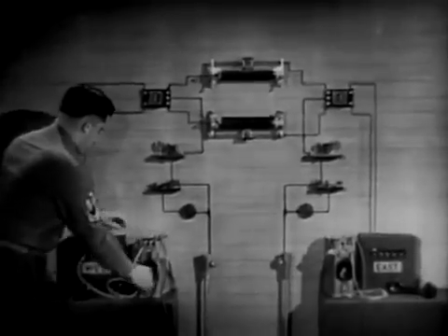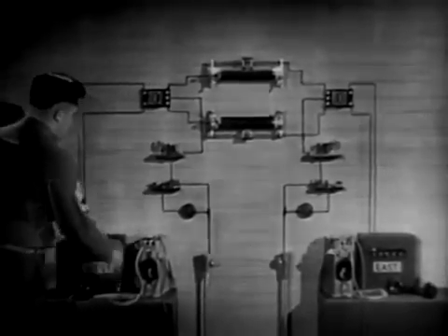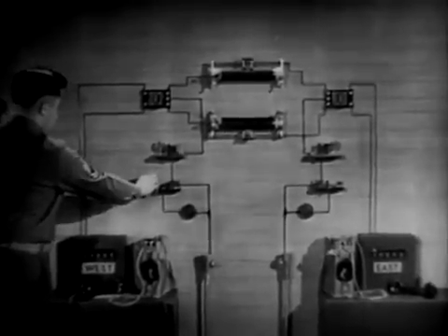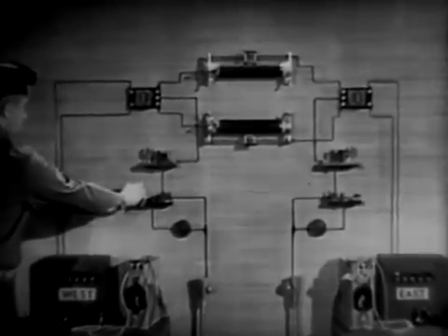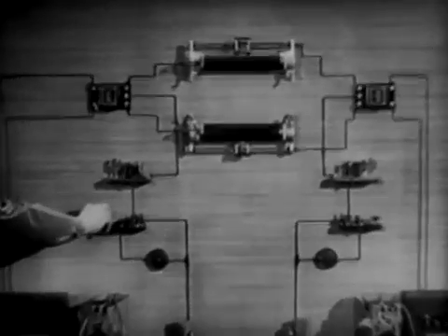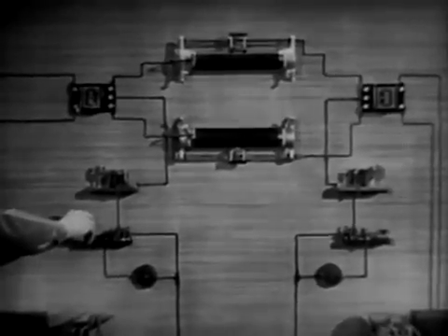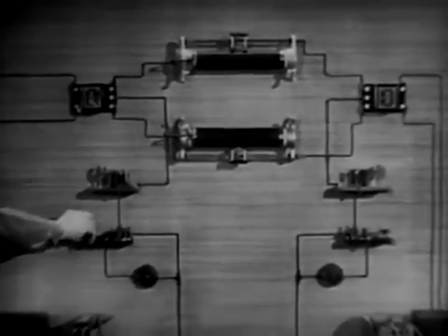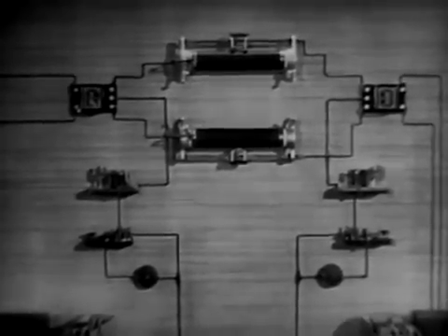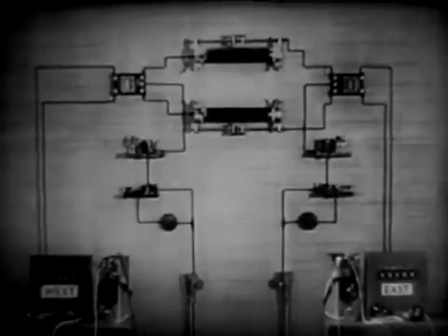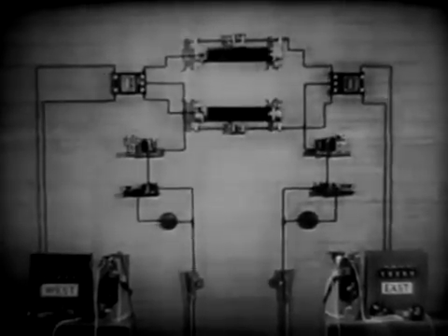The newly installed telegraph circuit can operate without interfering with the original telephone circuit. This new channel is a simplex circuit that may be used for either telephone or telegraph. It is rarely used for telephone, however, because like all ground return circuits, it is apt to be noisy. Here's how the whole thing works.